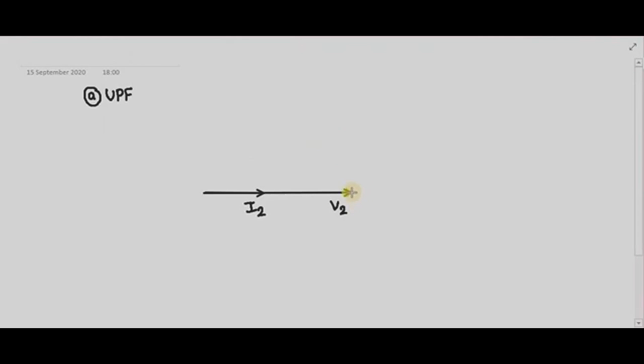So now in RT1 some drop will take place. That drop is nothing but I will write down this as I2 RT2. Then some drop will take place in the XT2. I am drawing this circuit for the approximate equivalent circuit of the transformer. Please keep this in mind. Right? So this is your I2 XT2, and phasor addition of I2 RT2 and I2 XT2 is nothing but